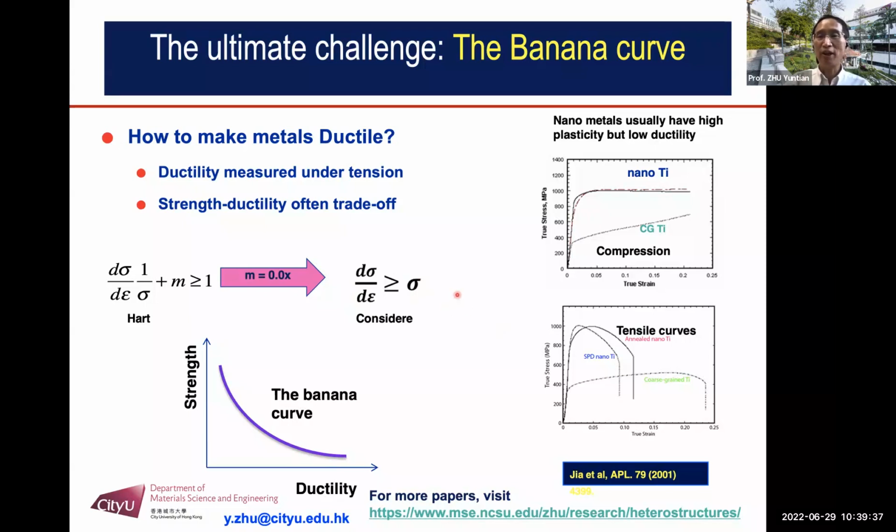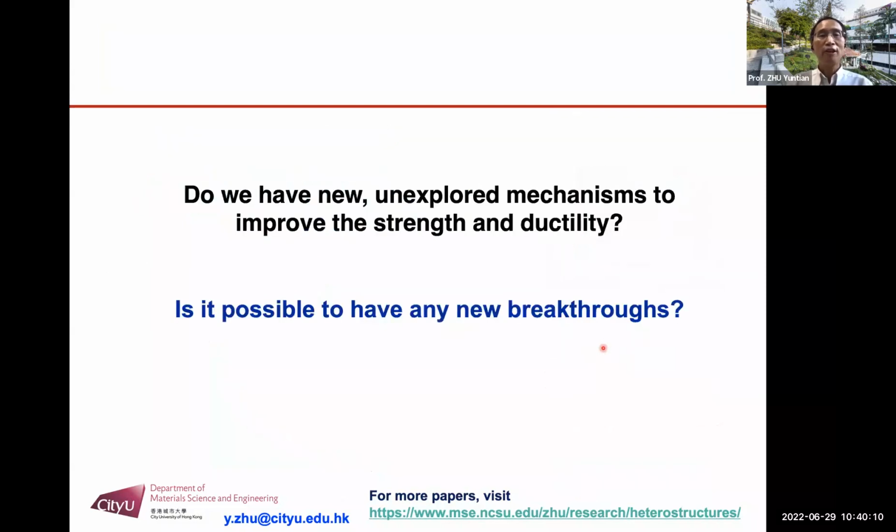So not surprisingly, if you test this titanium under tensile stress, you see it goes up under slow deformation. It started necking. The highest point, that's the necking point. Then this is all the necking strain. So necking strain does not count here because its length is sample dependent, sample geometry dependent.